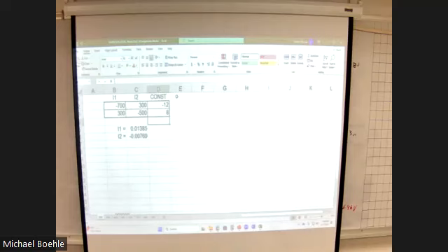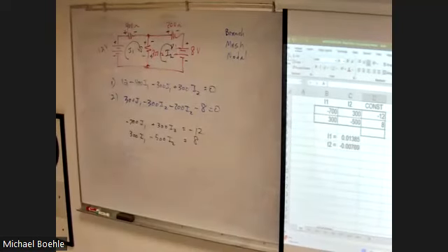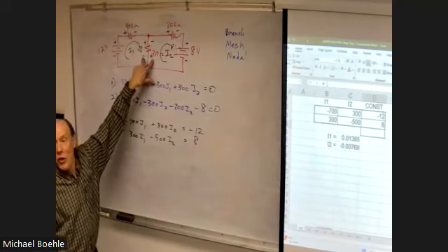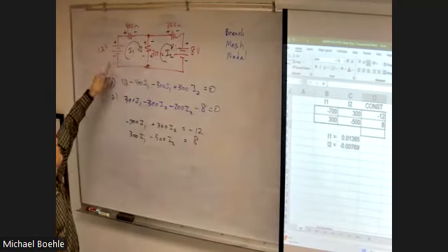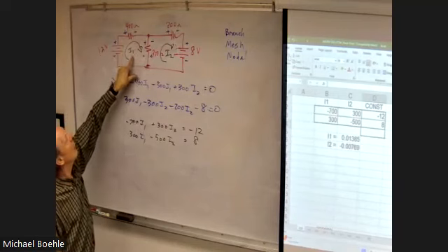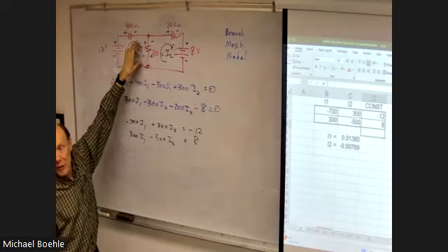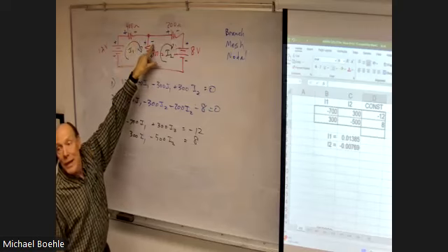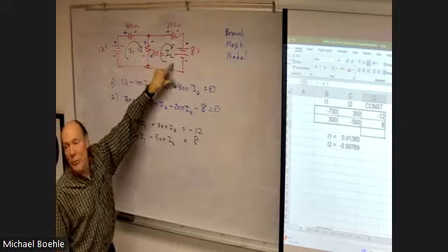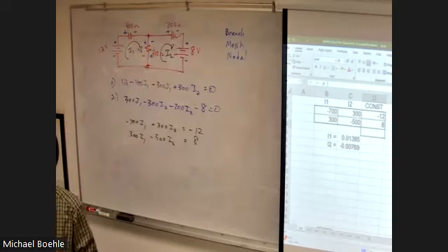Now, when it comes to doing the calculations, again, what was I looking for? I was looking for the current in, or the voltage across, the 300 ohm resistor. Well, that's always fun for this type of analysis because that's actually 2 voltages. Positive here, so it'll be current 1 times 300 ohms will be part of the contribution. And then negative 300 times current 2 will be the other part. So you've got to add those up. Well, negative times a negative becomes a positive.